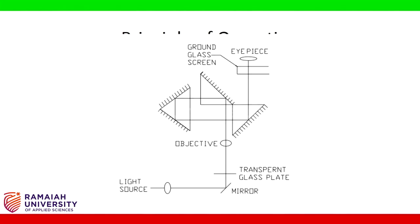A ray of light from a light source is reflected by a mirror through 90 degrees. It then passes through a transparent glass plate on which flat parts may be placed. A shadow image of the outline or contour of the workpieces passes through the objective of the optical head and is projected by a system of 3 prisms to a ground glass screen.